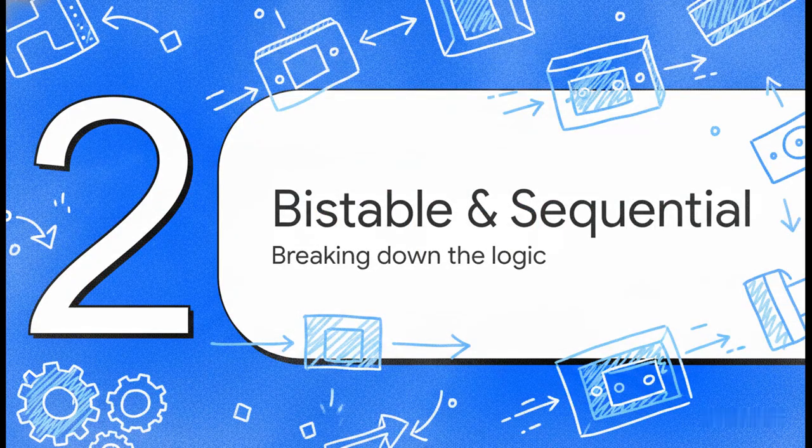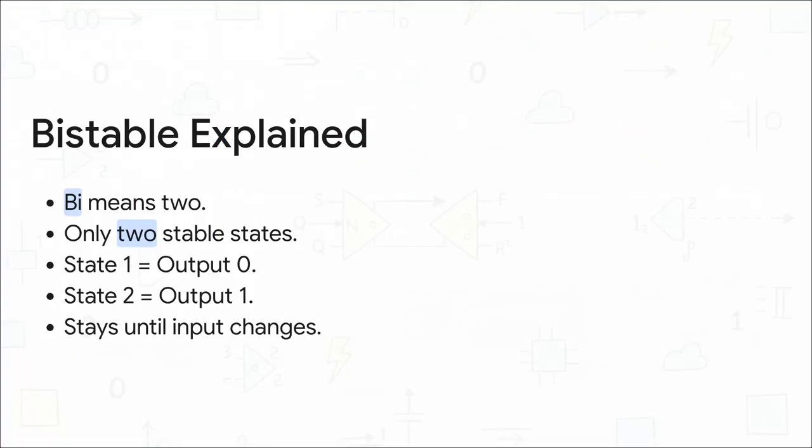Moving right along to Section 2, bistable and sequential circuits. So let's completely deconstruct that kind of intimidating technical definition into something totally logical. First, let's look at the word bistable. The prefix bi simply means two. So this circuit has exactly two stable states. State 1 means the output is a 0, and state 2 means the output is a 1. Now, the absolute beauty of a bistable circuit is that once it enters one of these states, it stubbornly remains there until a new input forces it to change. This persistence, this total refusal to change without permission, is precisely why we call it memory.